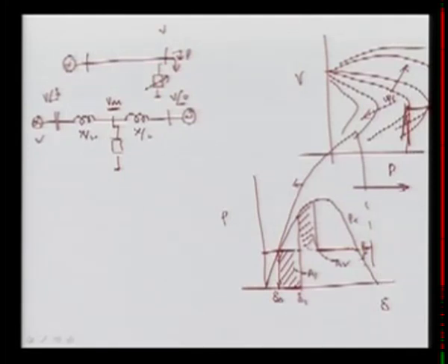Now you can see if you are having the compensator, this I explained without the compensator. Now if you are again operating here, there was some fault here, a three-phase fault, and the system was cleared at, let's suppose, this delta. Now you can say we are going up to this point, and this area we require only this much, and this is your decelerating area because this area must be equal.